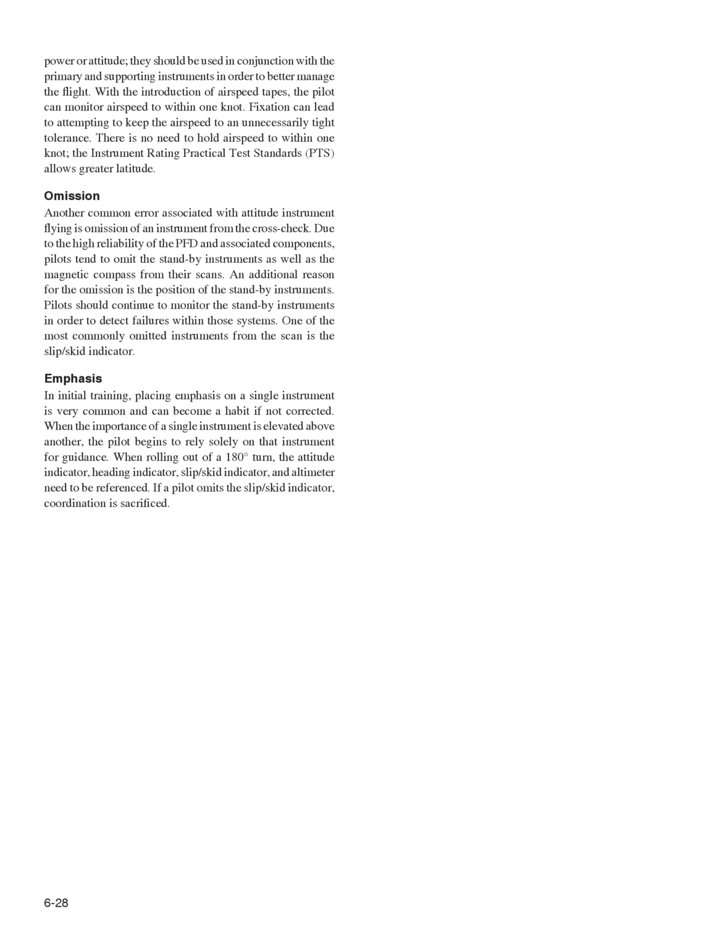Emphasis in initial training. Placing emphasis on a single instrument is very common and can become a habit if not corrected. When the importance of a single instrument is elevated above another, the pilot begins to rely solely on that instrument for guidance. When rolling out of a 180 degree turn, the attitude indicator, heading indicator, slip/skid indicator, and altimeter need to be referenced. If a pilot omits the slip/skid indicator, coordination is sacrificed.